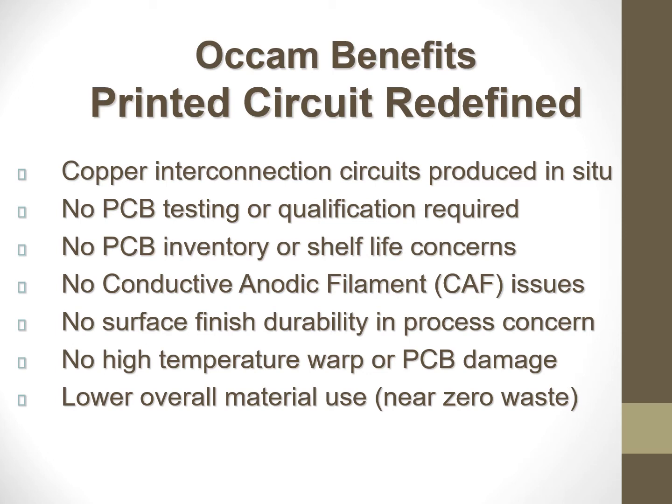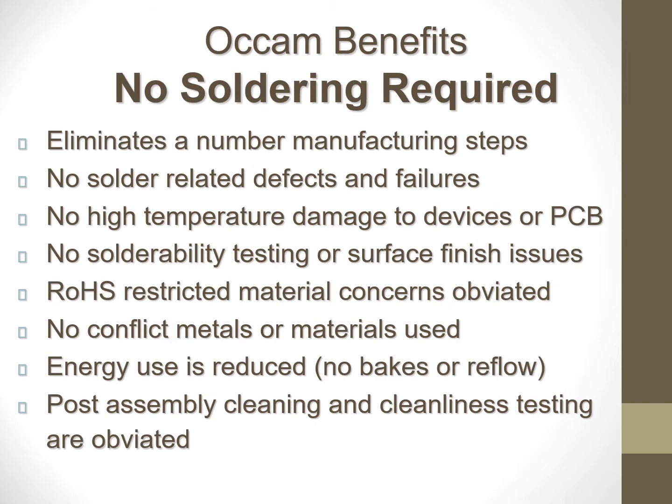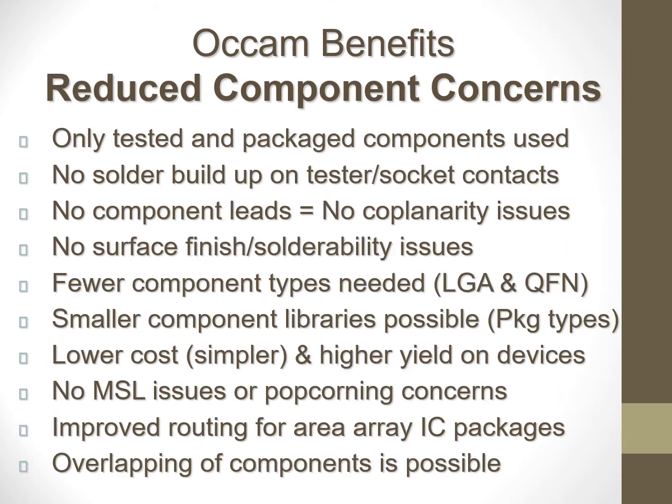And then there's lower overall material use. There's no soldering required, so again, that eliminates all the manufacturing steps that were just described, and no soldering related defects or failure, none of the damage that was described, no solderability testing, no concern about RoHS restricted materials, especially lead, no conflict metals or materials are used in this. The energy consumption is significantly less, and post-assembly cleaning and cleanliness testing are obviated.